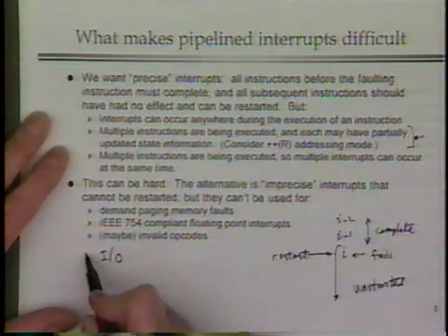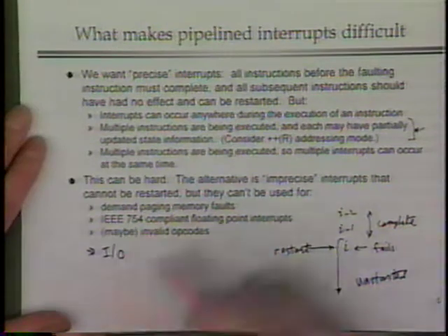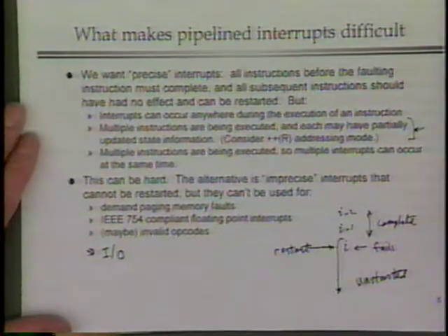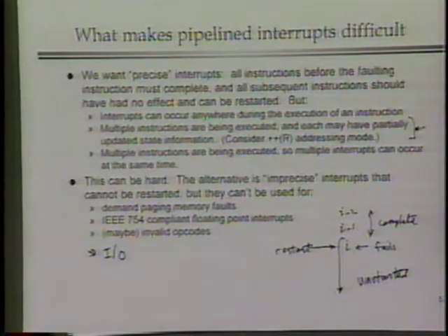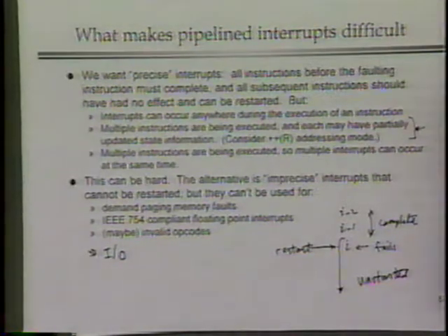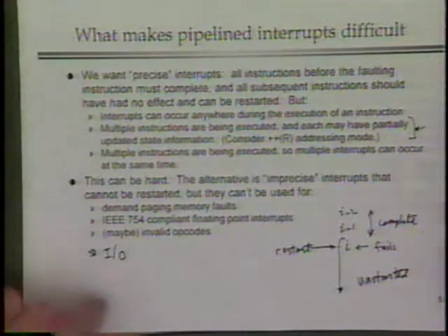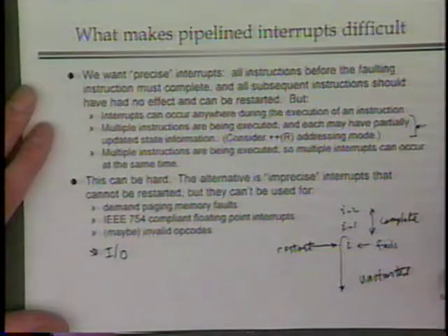You don't have, let's say, an I/O interrupt. I mean, if every I/O interrupt threw all the instructions out of the pipeline. Oh yes, okay. That you certainly need to add as an interrupt that has to be precise, as an I/O operation. Those are sort of the easy cases because you get to decide where you want to take that interrupt exactly. Right? You can just stop feeding instructions into the pipeline, wait for the pipeline to be drained out, and then take the I/O interrupt. You've just taken a few cycles delay. So getting precise interrupts for I/O is not such a big deal. Getting precise interrupts for faults that are internally generated within the instruction while it's executed is a much bigger deal.